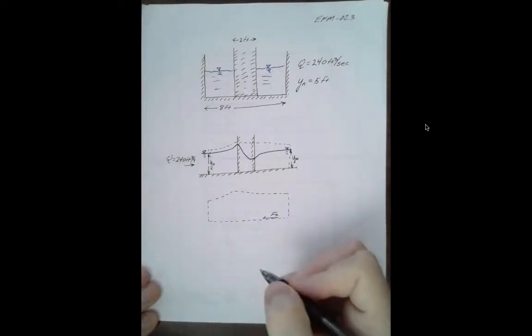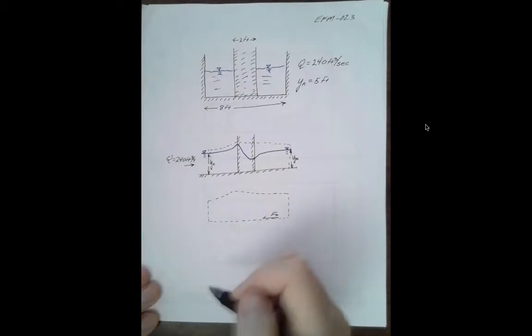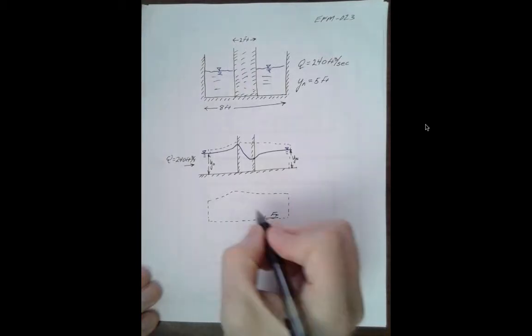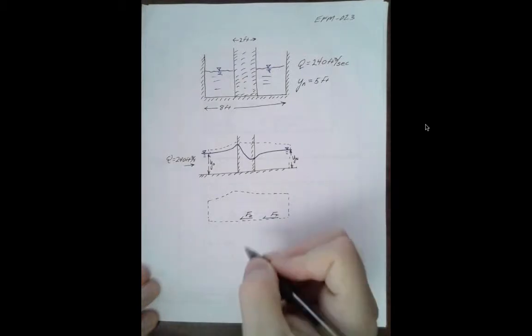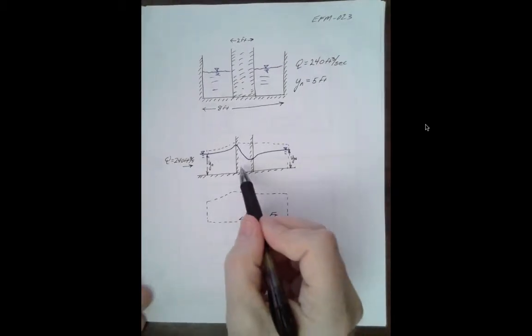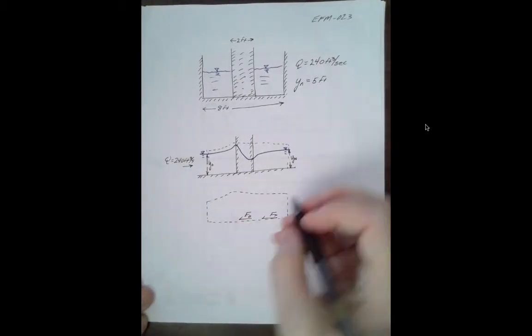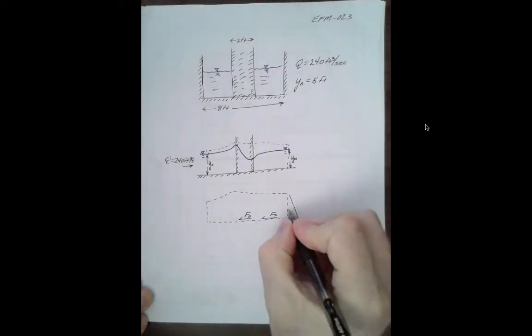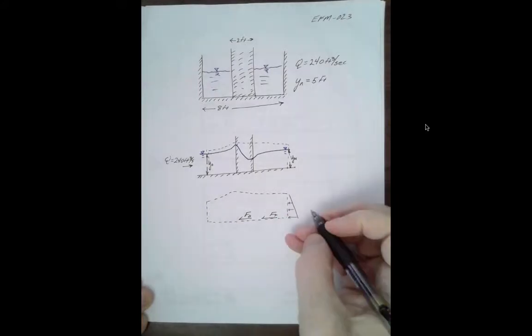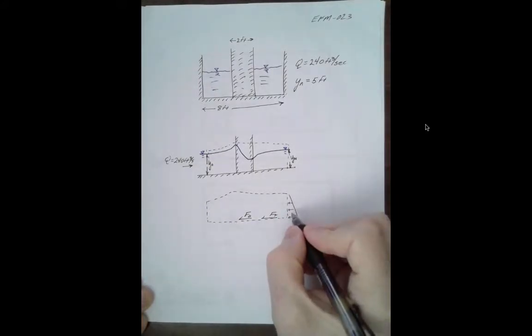There's some frictional shear from the water contacting the sides and the bottom. There is a drag force induced by the pier that pushes on the water. There's the assumed hydrostatic pressure distribution on this end, which produces a force